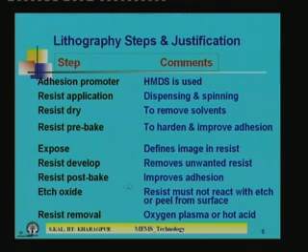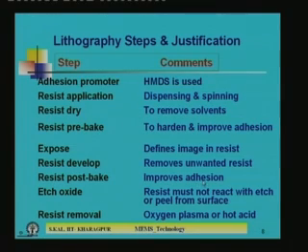After the resist develop, you are putting the whole thing in the liquid. So, that developer solution will be there on the surface of the photoresist as well as the substrate, and some of the developer solution will be absorbed by the film. As a result, the photoresist film will be soft, and again you have to dry it before going for actual silicon dioxide etching. During that drying, which is known as post baking, the photoresist film will completely adhere to the substrate. So, that will improve adhesion.